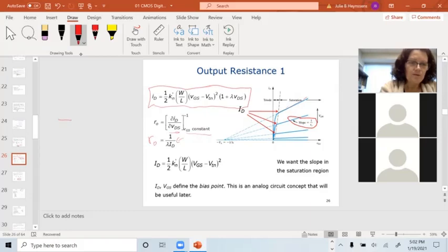So my model of the transistor for small signal looks like this. I have an AC VGS. This is the gate. This terminal must be the source. And what's left over is the drain. I have something we haven't talked about yet. I have a dependent current source. We talked about it in 280. It's some constant GM times VGS. And I put a resistor across here, little RO.